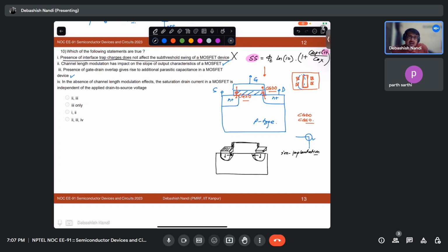These are in some high end ferroelectric field effect transistor structures. Keep in mind that there are some exotic new structures and manufacturing processes where these overlap capacitances can be avoided. But those may not be for mass production or a huge number of transistors. There may be some specific niche applications.